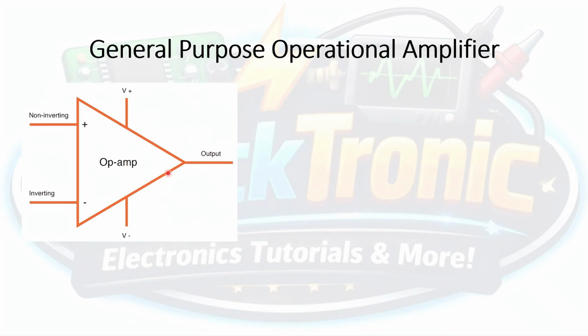The operational amplifier, or op-amp, is represented by a triangle with 5 pins sticking out of it. Now, the 5 pins are as follows. Here on the left side are the inputs. As you can see here, there are 2 inputs. One is non-inverting, represented by a plus sign, and the other is an inverting input, represented by a minus sign. On the right side, we have the output, a single output.